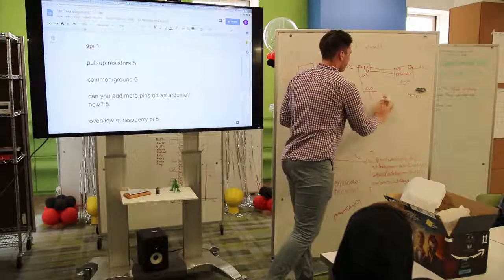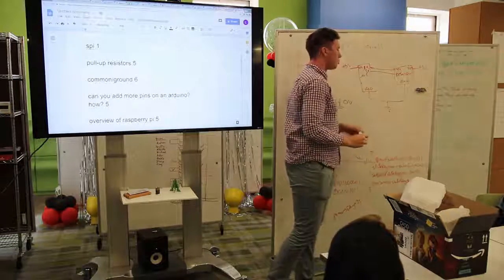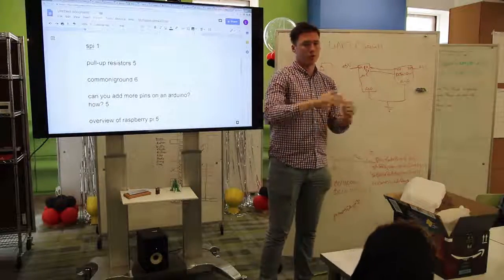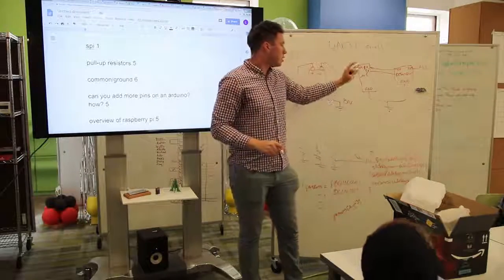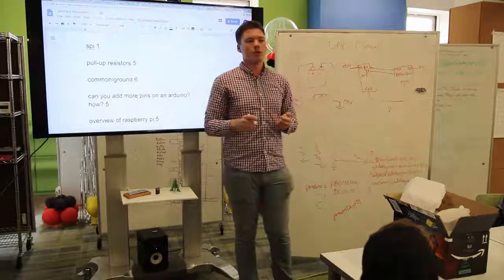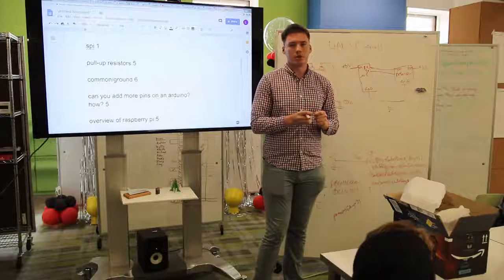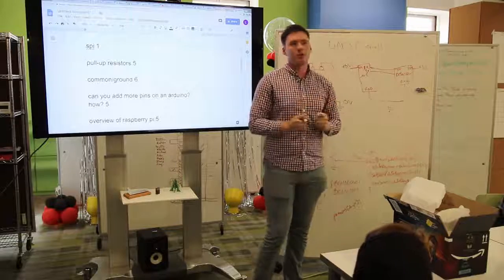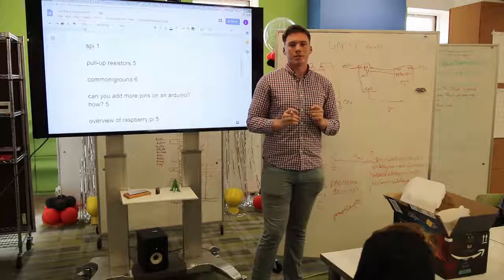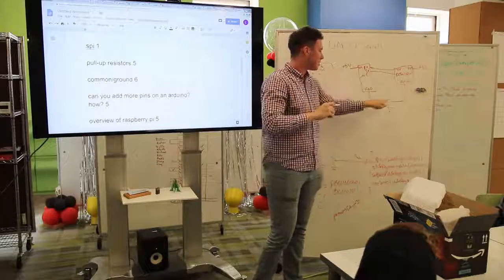When you connect them together though, now they're working from the same starting point, which means when they send 5 volts more, the other one understands that's 5 volts more. This is 0, this is ground. Does that make sense? Not tying your grounds together is one of the most common problems you will run into when trying to get separate electronic devices to work together. In university, I've seen senior electrical engineers stumped on a problem for weeks and then realize they forgot to tie their grounds. It happens a lot, so this is important.